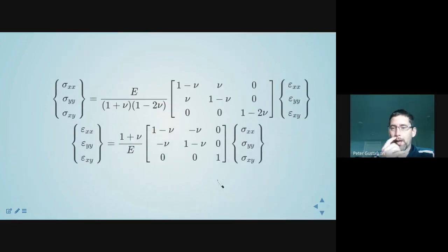And lo and behold, when you go through and propagate that into the equations and calculate your new effective C and S matrices, now in 3x3 terms, you're not calculating the stresses that may be present. When I say ignoring, I'm saying you're not calculating them. You're treating them as if they exist, but you're not calculating them. You can therefore calculate the stress and the strain using this smaller set of constitutive equations. Again, it simplifies the problem.